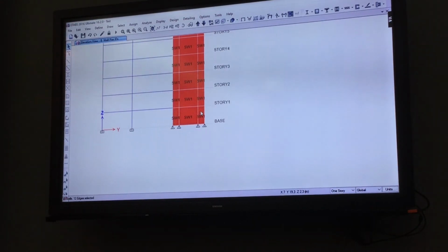Then you can decide same as before, but this time you will get the reinforcement ratio, and that ratio you have to distribute according to the rebar layout that you define in the section design. That portion is complicated.